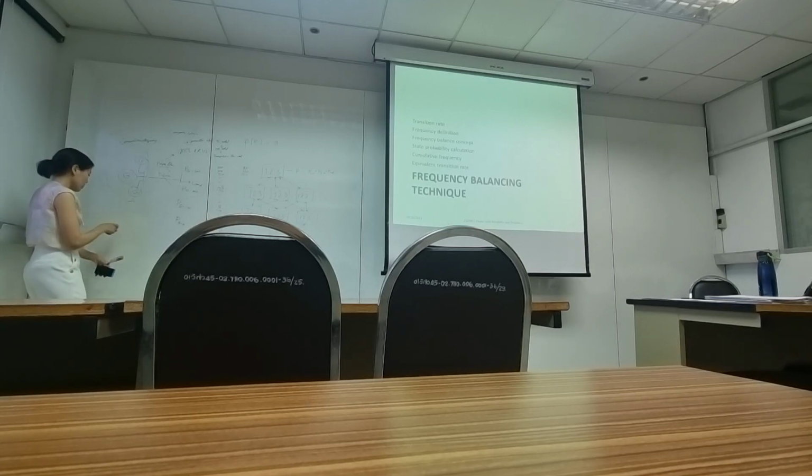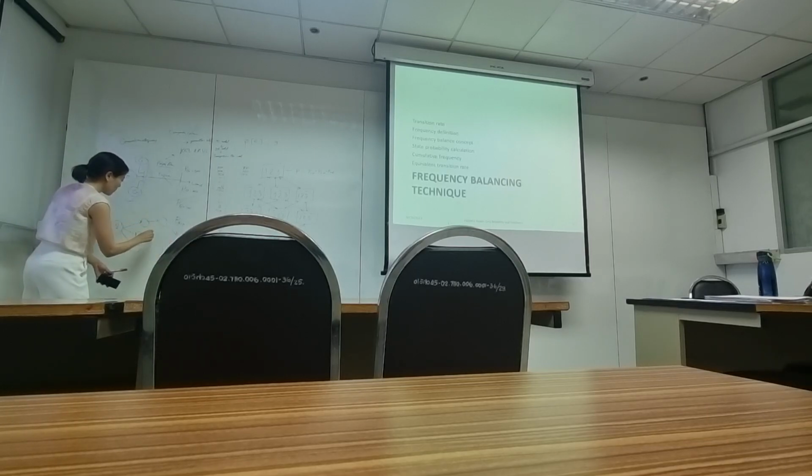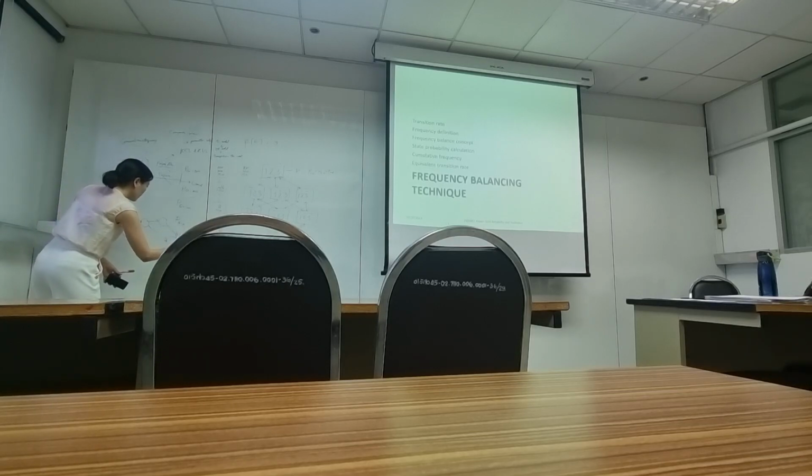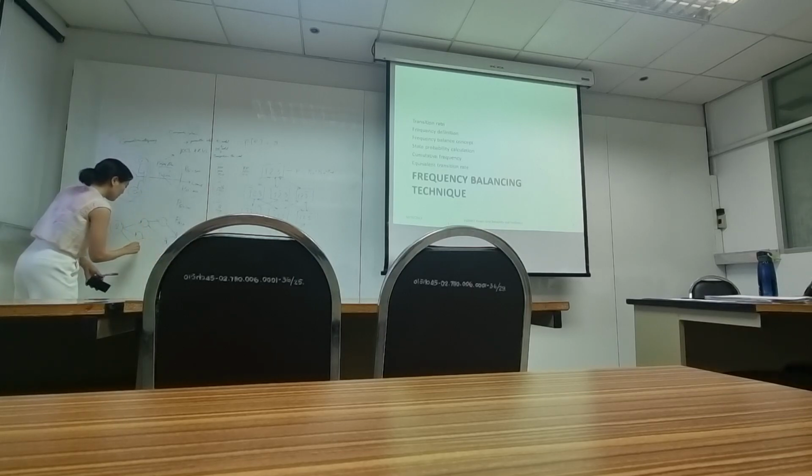reliability block diagram of different nodes, giving you the source right here, which is the generation, and then you have the network points that represent the different nodes of your system, and then you have the sink node. Okay.